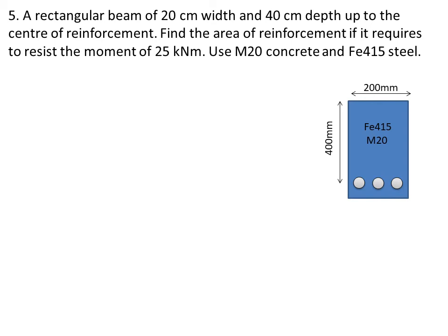Fe415, M20, 400 mm. See this depth from the top to the center of reinforcement is the effective depth.